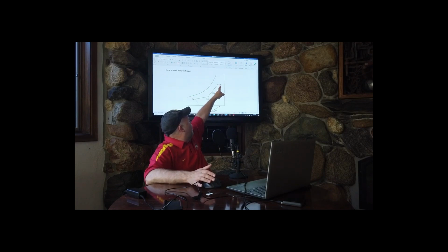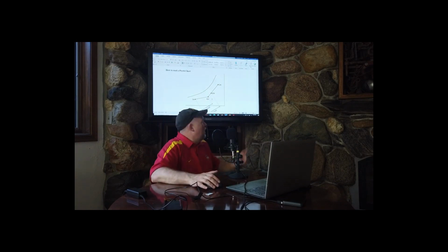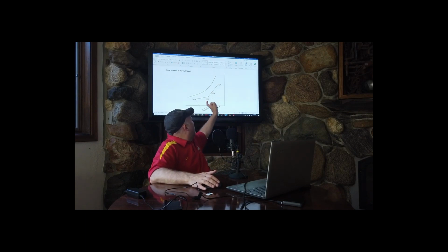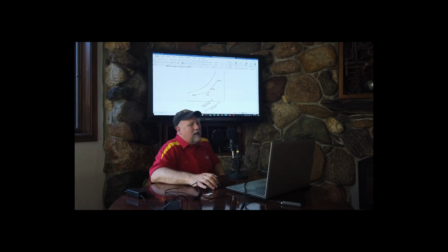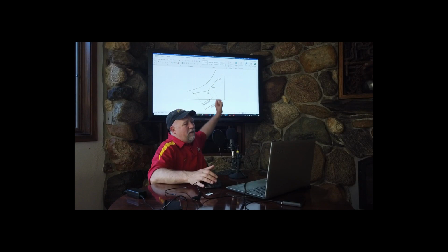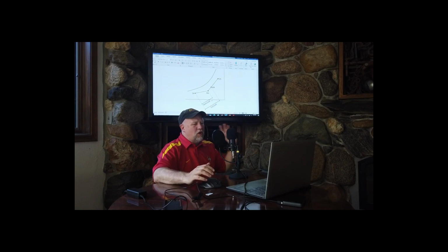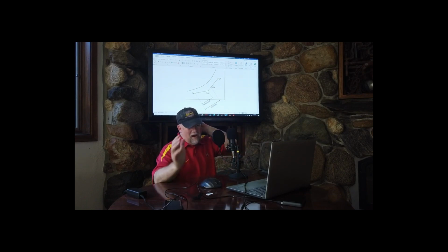If this outside air point is 95 degrees, 78 degrees wet bulb, the mixed air is a mixture of the two. In other words, somewhere on the line that we're going to plot between return air and outside air, this mixed air is where we're going to be in terms of conditions. Warmer and more humid than the space, but not as bad as the outside air. Where this mixed air falls on this line is a function of the percentage of outside air. In other words, we're going to calculate it. What is our total CFM? And then what is our outside air CFM?